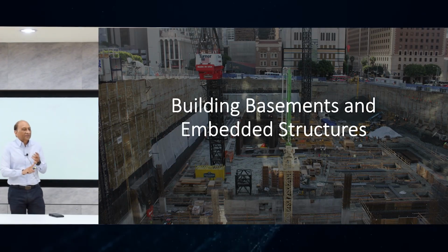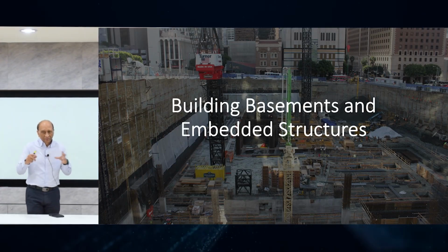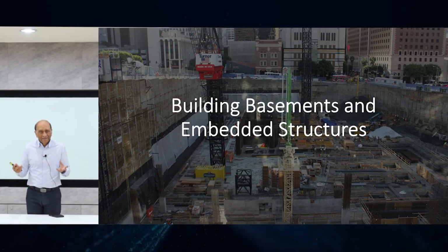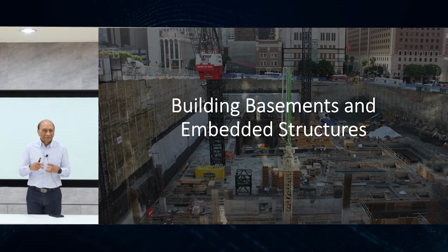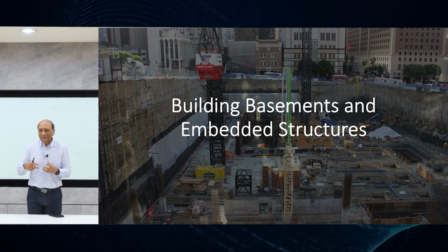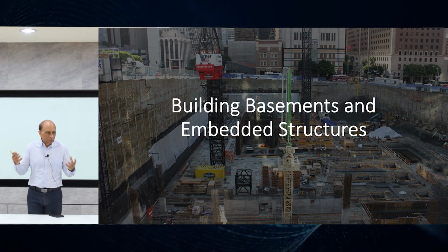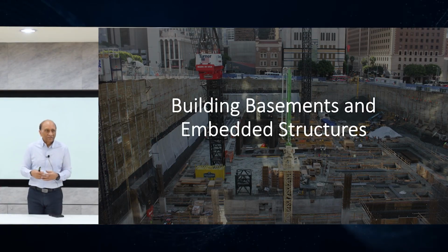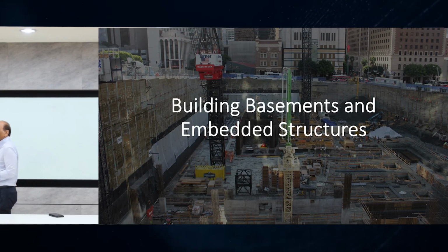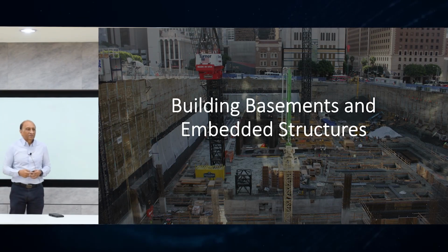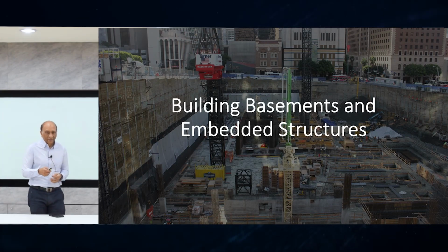So first lesson is that the foundation loads and structure moments, they are interconnected, and soil structure model will tell us the right ones. The other one is that soil bearing capacity is actually related to size. So you need to get the correct bearing capacity in the first place. And third one is that we should not specify the direct settlement on the structure.